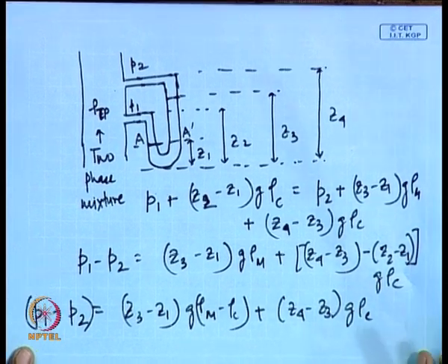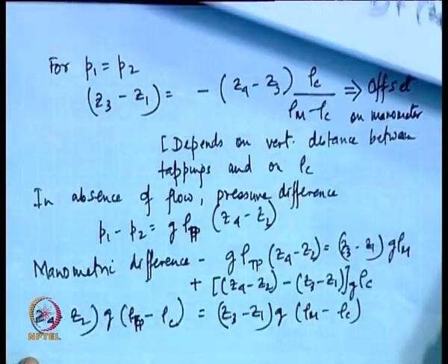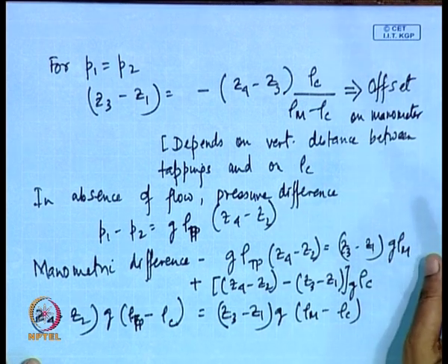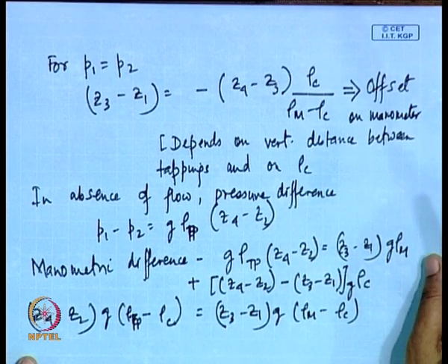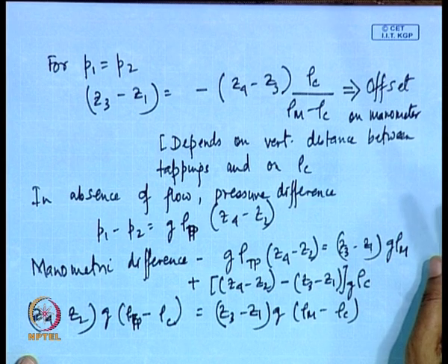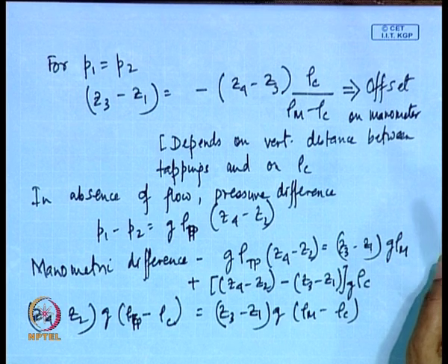So, pressure drop measurements can be more accurate and the offset is less for gas filled lines, but the pumping action is so very high and the tendency of liquid entering into gas filled lines is so drastic that for most cases we do not prefer gas filled lines, we prefer liquid filled lines, unless some very special circumstances or applications force us to adopt gas filled lines, correct.